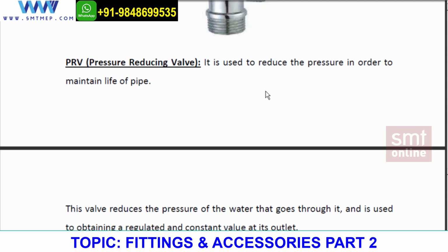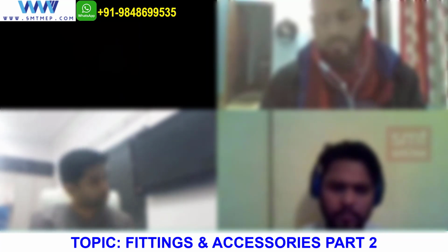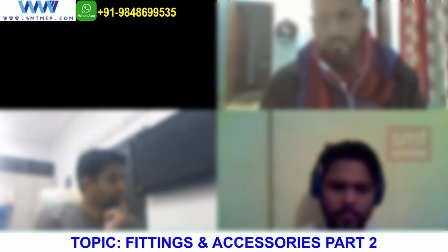because if you see the pipe online, as per ASTM or something, some PSI is written on it. Have you observed this? On any kind of pipe, UPVC, CPVC, on any plumbing site. Or check in our households, in the risers, something in PSI is written. That means this pipe can bear this much pressure only, not more than that. If it is more than that, it will burst.